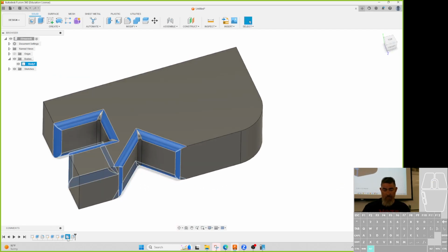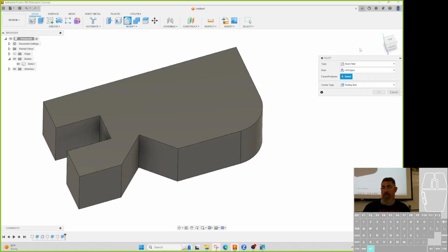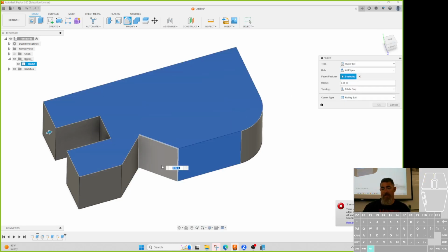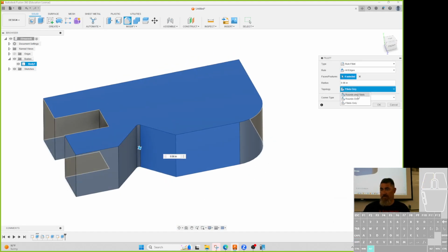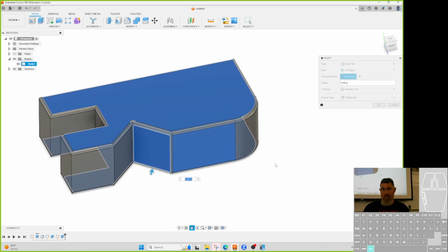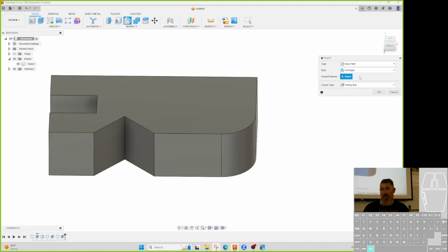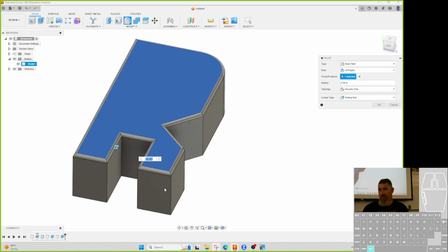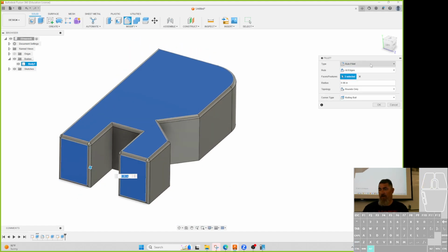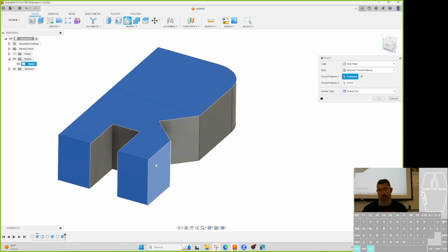Or it could be just the rule fillet between this face and those faces. It's fillet, so it's going around the edge. But if I did just between this face and those faces, between facing edges. There we go. So if I do between faces and feature, I pick face 1 and then feature face 2.